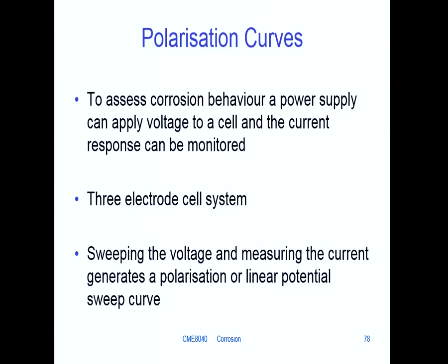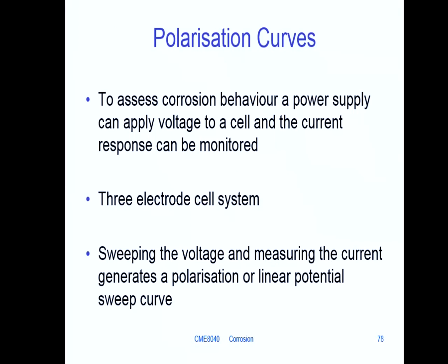So if you want to find out how your pipe steel behaves in a particular environment, you start off by creating a known surface area electrode of your steel.